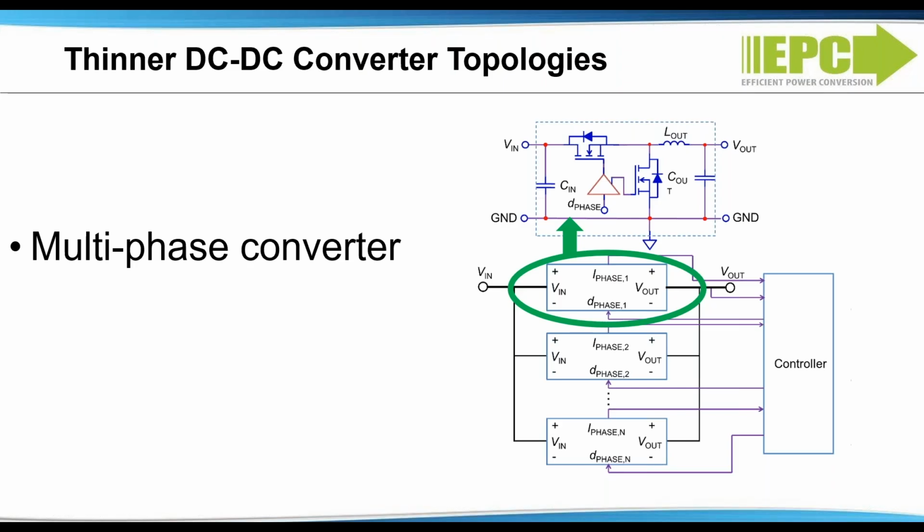One topology option, the multi-phase converter, is composed of multiple interleaved synchronous buck stages. This solution allows the use of thinner inductors by distributing the output power processed by the single large inductor in the synchronous buck converter among multiple small inductors. This, however, may not address the loss and thermal issues on the inductors, as the volt-seconds on each inductor remains unchanged.